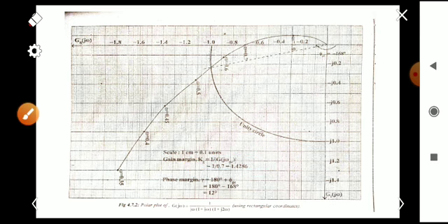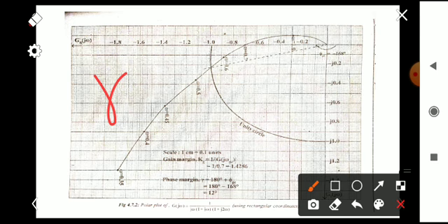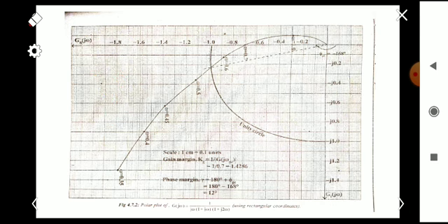And after that, for finding the phase margin, our gamma equation will be 180 plus phi gc, same equation as in the Bode plot. For finding the phase margin, the first step is to draw a unity circle, that is, combining the minus 1 value here and minus j 1.0 here.